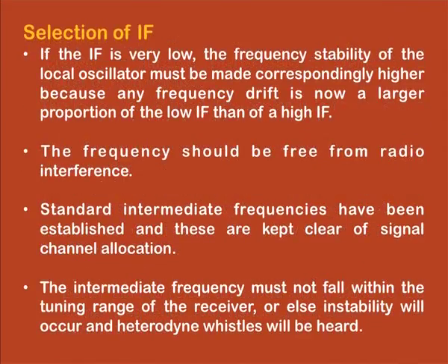If the IF frequency is very low, then the frequency stability of the local oscillator must be made correspondingly higher, because any frequency drift is now a larger portion of a low IF than of a high IF. The frequency should be free from radio interference.